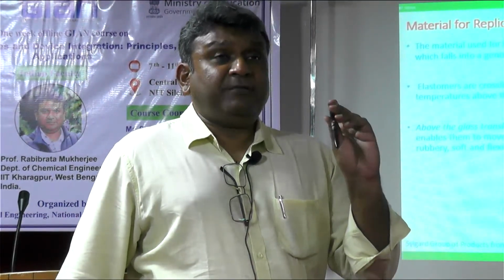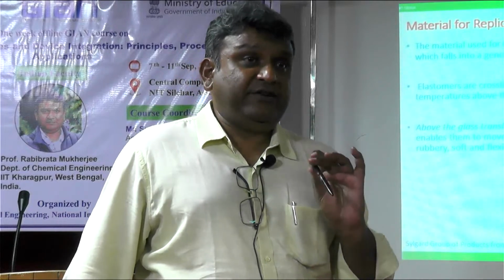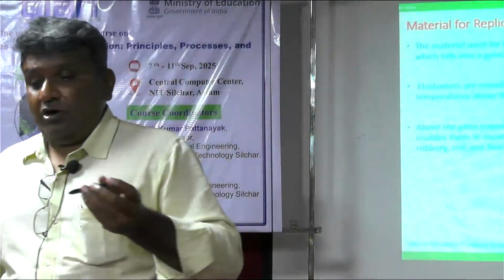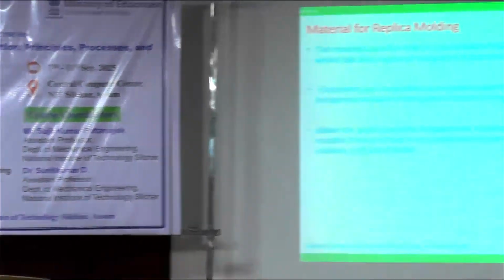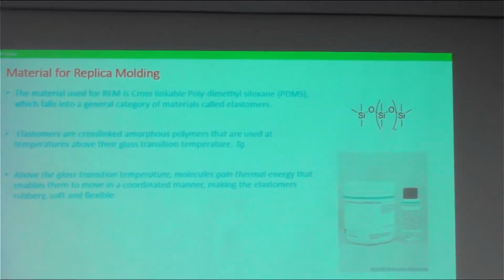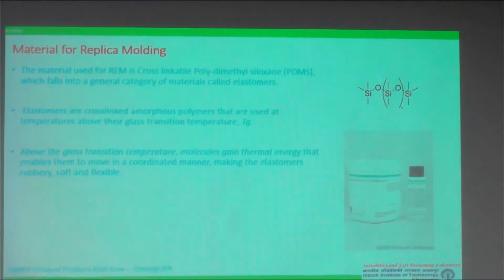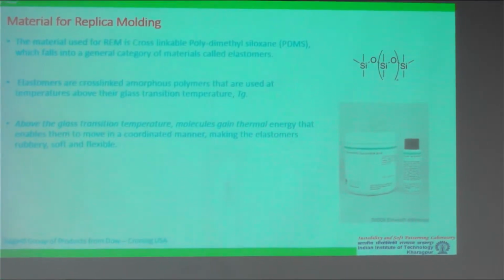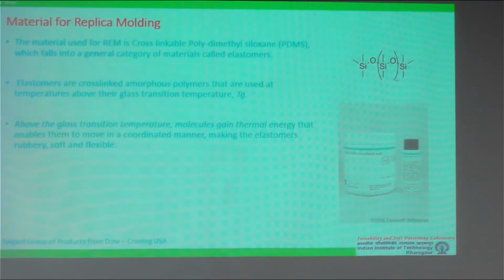The type of polymers which are solid-like at room temperature are called glassy polymers. Now, why are they called glassy polymers? Because, as you know, most solid materials are crystalline, right? Most metallic materials are crystalline. But glass, I guess you know, is not a crystalline material. It's an amorphous material. But then how is it solid at room temperature? Glass is often called a supercooled liquid.